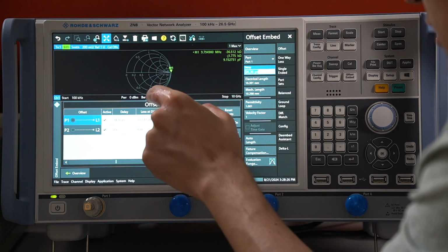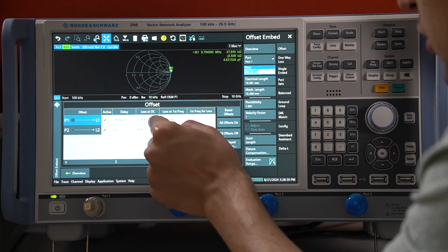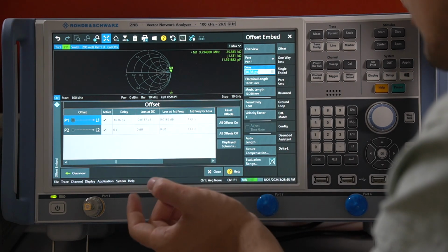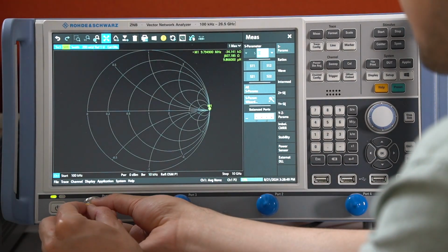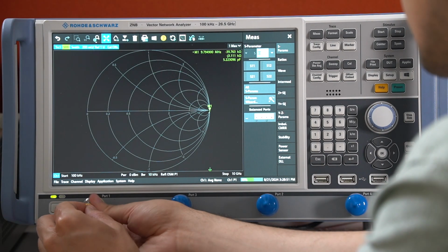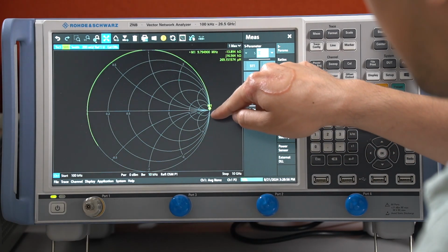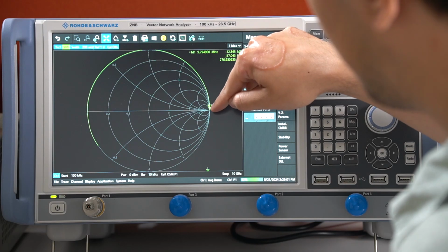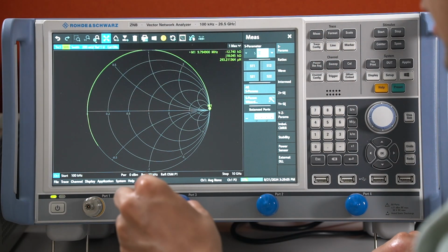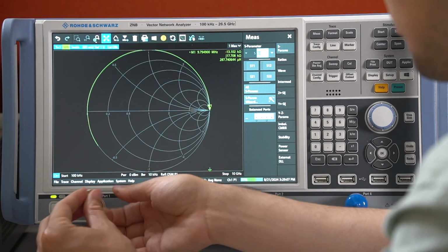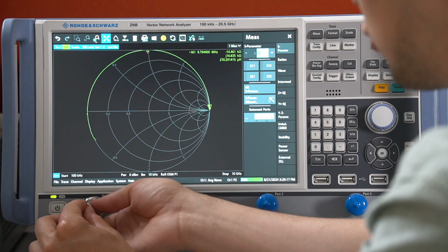And then in addition to our delay, it also introduced here a factor for correcting the amplitude. Now let's go back to our measurement. We unplug our SMA connector, and we should now see again a line, but this time counterclockwise. And now we will plug in our capacitor mounted on our SMA connector, and this time the phase should be correct.